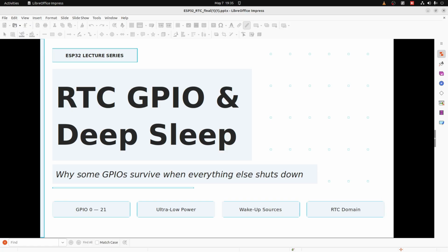We will understand why certain GPIOs on the ESP32 stay alive and functional even when the entire chip is essentially shut down. Which are those pins and what wake-up methods are available to us? You will also notice we mention the ULP, the ultra low power coprocessor in this video. The ULP is a powerful topic on its own and it will get its own dedicated portion later in the series. For now, just know it exists and that it lives inside the RTC domain. Let us get into it.